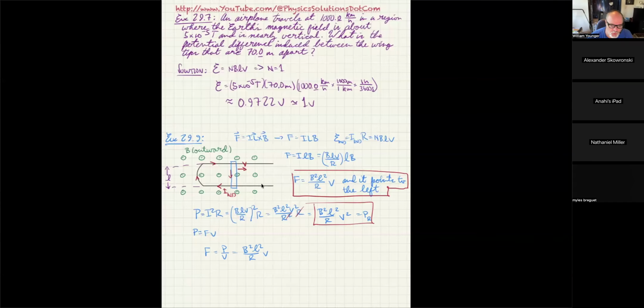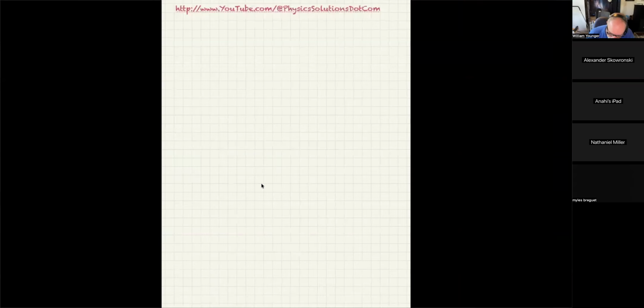So let me show you what a generator actually does. Your book actually has a pretty good figure of it. You can imagine a coil, a loop of wire, if you will, that's free to turn. They've mounted it on an armature, so they have a cylindrical object, and then from that center of the cylindrical object is like an axle sticking out both ends. And you could actually put that axle on bearings, and that would make it nice and smooth. And then you could use some mechanical methods to actually rotate that armature.